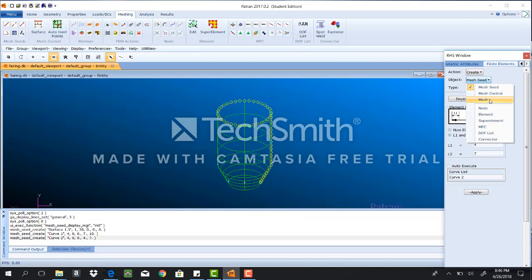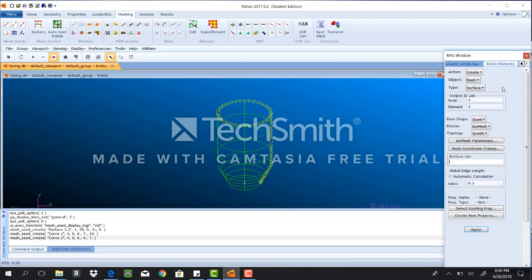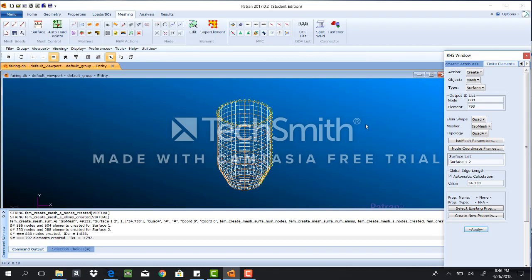After that, we go to create mesh surface, quad, isomesh, quad 4, and select the surface 1 and the surface 2. We're going to leave the automatic calculation and then apply it.